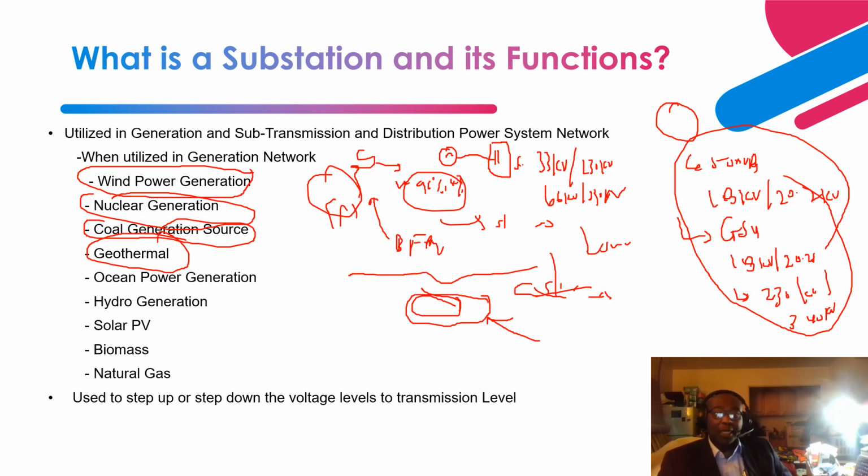to the generator rotor. So as the turbine shaft rotates, since it is coupled to the generator rotor, the generator rotor automatically starts rotating, and a magnetic field is created on the generator rotor from an excitation system.